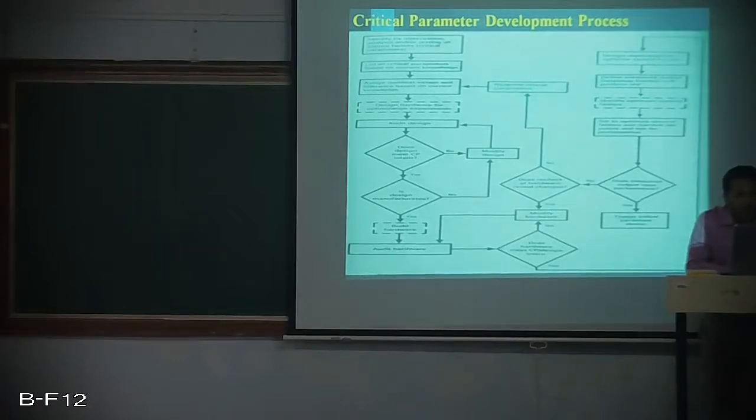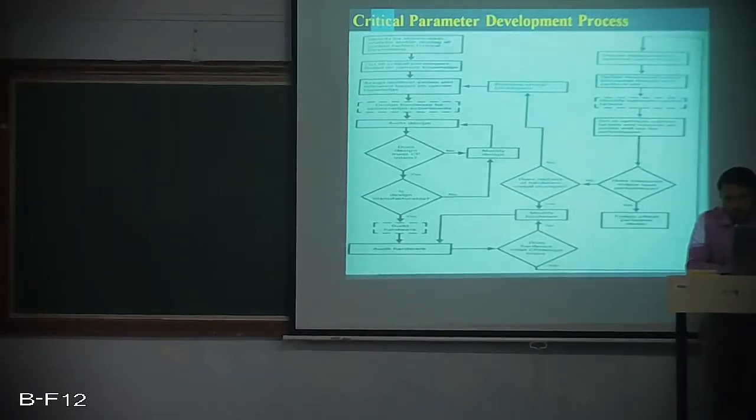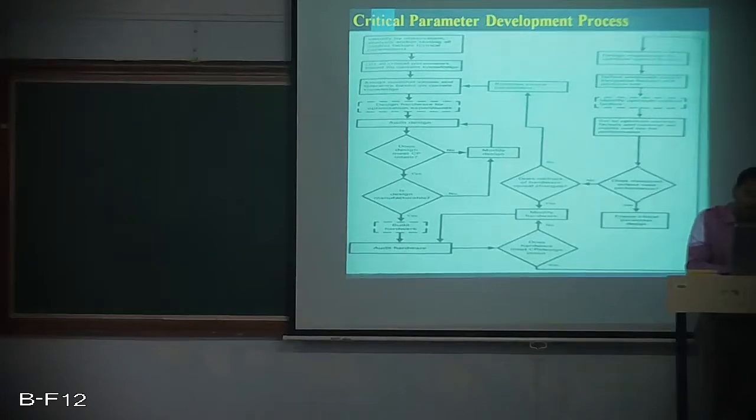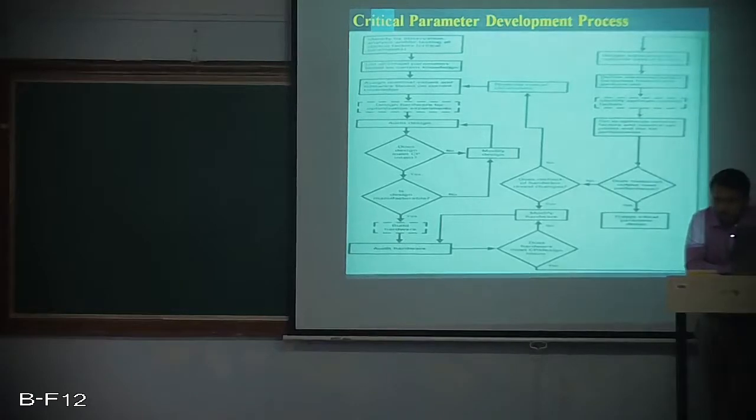Then assign nominal values and tolerance based on current knowledge. So you need to assign the nominal values for those critical parameters, and also importantly you need to assign the tolerance based on your knowledge. And then design hardware for optimization experiments, and you need to design the hardware for optimizing these critical parameters.